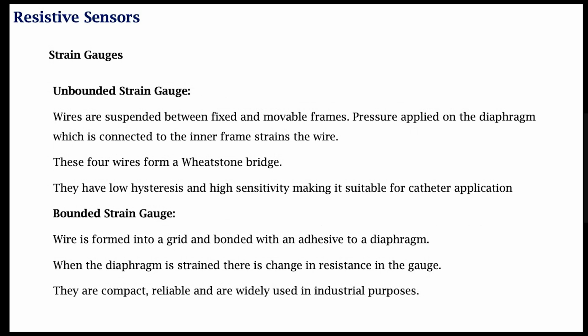These wires form a Wheatstone bridge, and you can measure the voltage across the resistors of interest to measure the changes in strain.